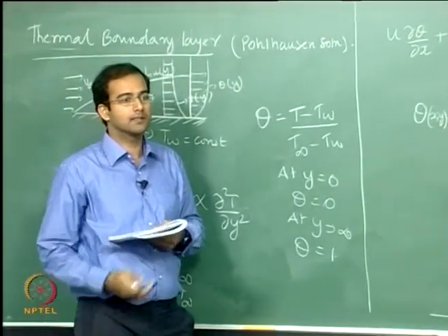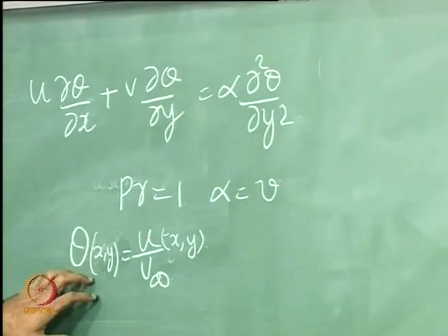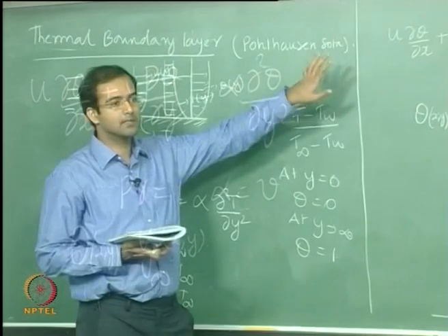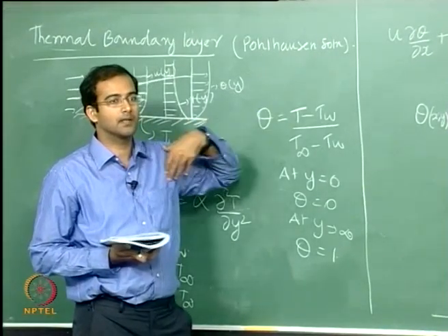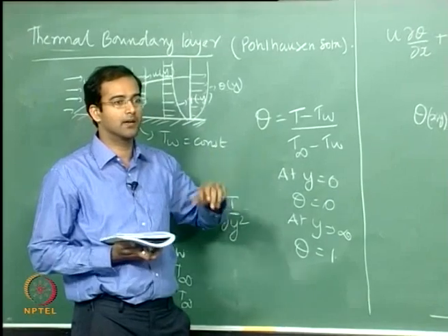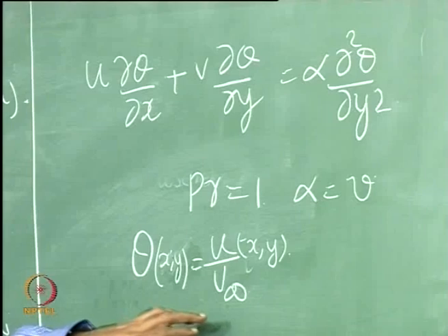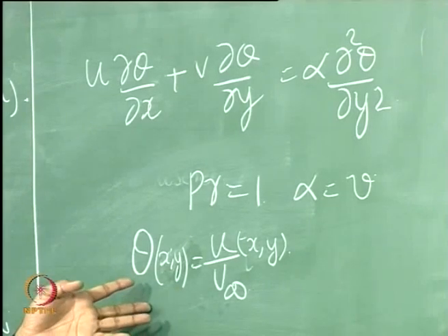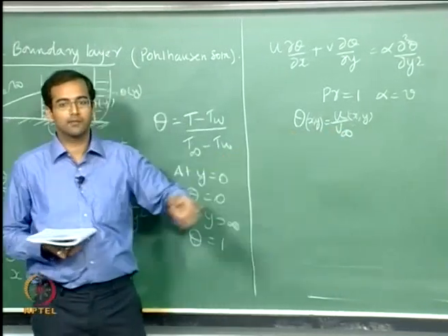Okay, so this is a very important conclusion. For a flat plate case, in the momentum equation you don't have any pressure gradient, and if you non-dimensionalize the energy equation, the non-dimensional forms of the momentum and the energy equation are exactly identical when your Prandtl number equals 1. Now when Pohlhausen looked at it, he knew directly he had the solution for Prandtl number equal to 1. The profile that you have already derived for velocity is the same.